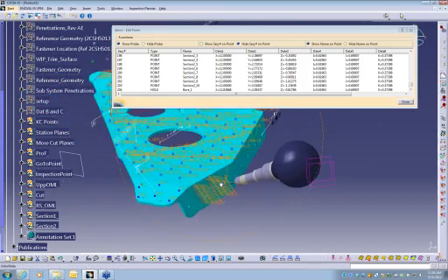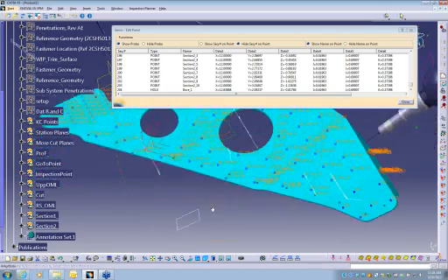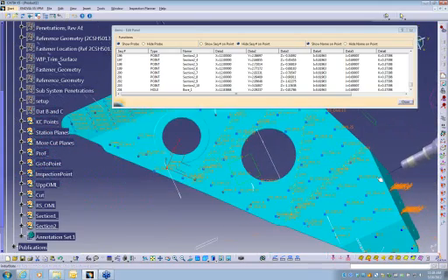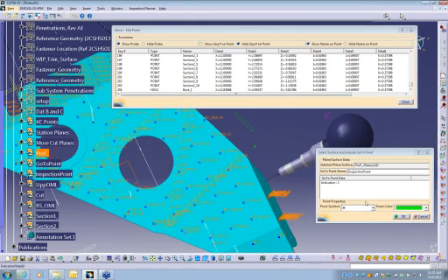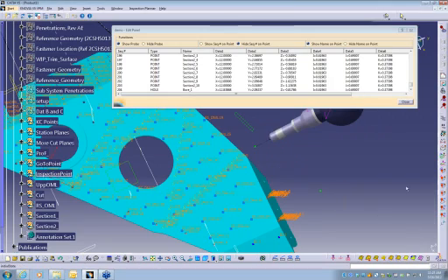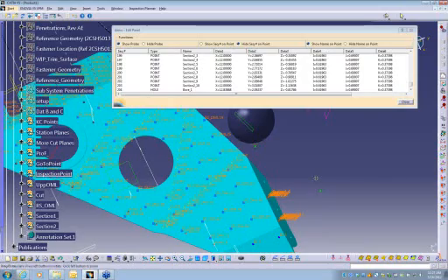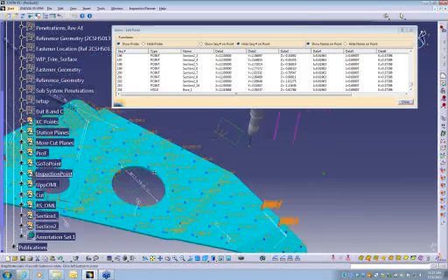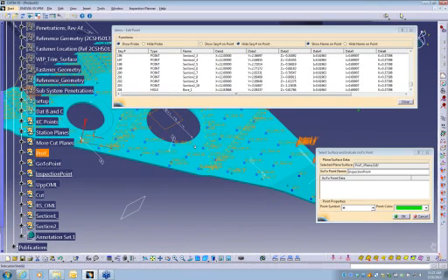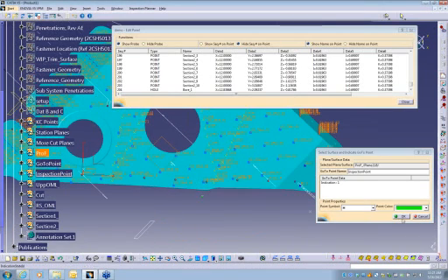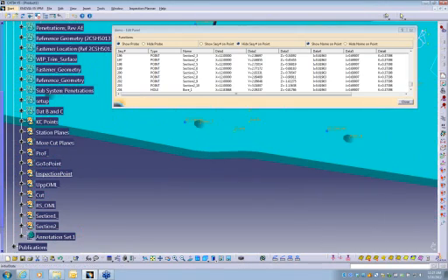If we want to do some probing around an edge of the part, let's kind of come in. We'll show you one more way we can do profile of the part. So let's come in here. We'll lift the probe back up to maybe here. We'll just come in here. We'll do a 0-0 change. We'll go to here, and we'll do another go-to move over to right here. And now let's say that I want to probe the periphery of this part.